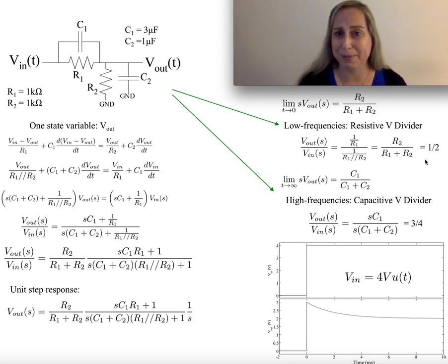How did that happen? And it turns out that, yes, indeed, the capacitive divider, it's almost as if the resistors were not there. What you see with the capacitor divider is that, in fact, for an input step, it's the capacitor divider that is the primary thing first, and then eventually there's dynamics that lead you back to the resistor divider. So for 3/4, you would expect that a jump of 4 volts puts me up to 3, and then this has a drop down to 2 volts.